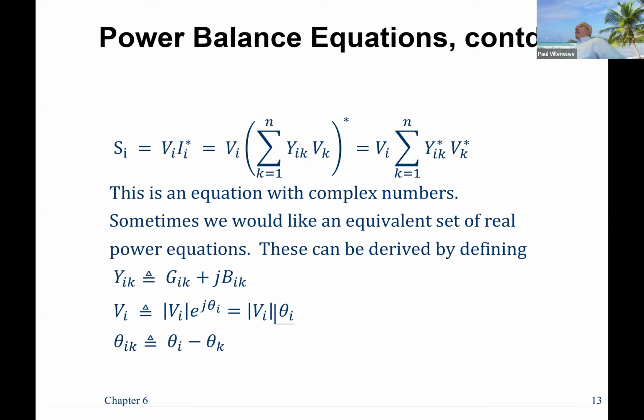So the same thing here, we have to take our Newton-Raphson equations, our power balance equations, and convert those to purely real numbers. And how do we do that? We just start breaking up the bus voltages and the terms of the admittance matrix into their real and reactive parts, or their magnitude and angle parts.